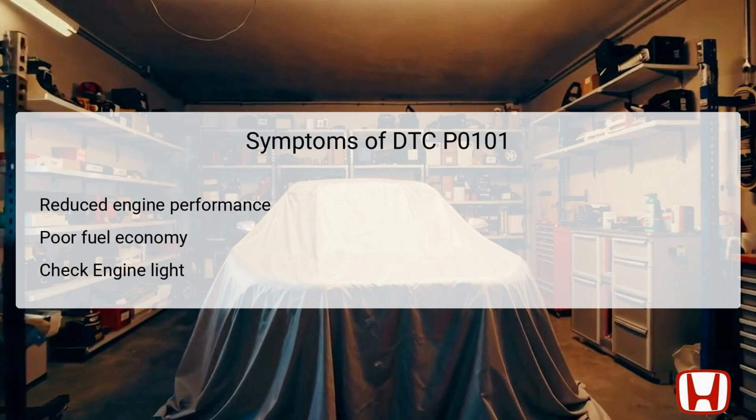One of the most noticeable symptoms is reduced engine performance, characterized by sluggish acceleration and hesitation during driving. Additionally, poor fuel economy could arise due to inefficient air-fuel mixture calculations, leading to excessive fuel consumption.